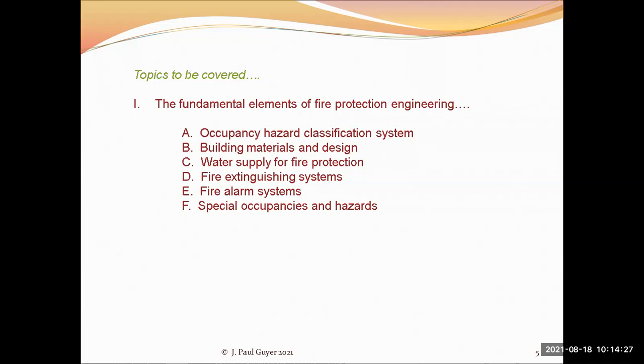We'll talk a little bit about building materials and how they fit into the fire protection picture. Again, I said I'll spend some time chatting about water supply for fire protection, and where you, if you go through and do an estimate or a calculation of the water supply that you will need for fire protection purposes for your building, and you find out that you don't have that quantity of water available, either from the local water utility or maybe from some other source, well, then you're in the position of needing to store water on the site of your project for fire protection purposes.